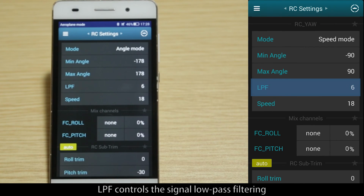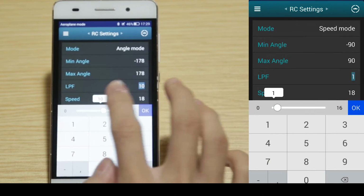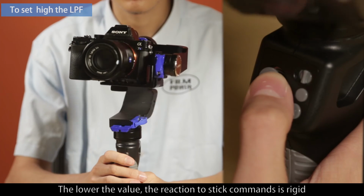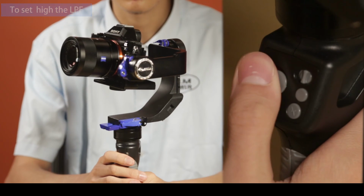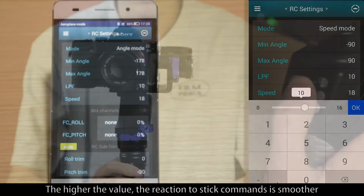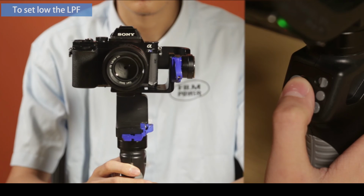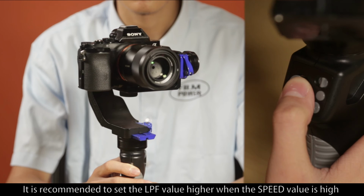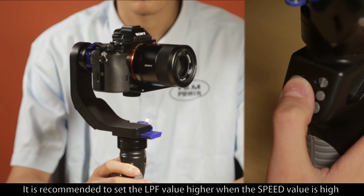LPF controls the signal low-pass filtering. The lower the value, the reaction to stick commands is rigid. The higher the value, the reaction to stick commands is smoother. It is recommended to set the LPF value higher when the speed value is high.